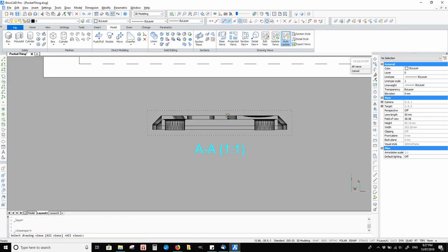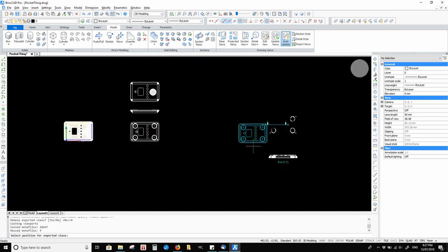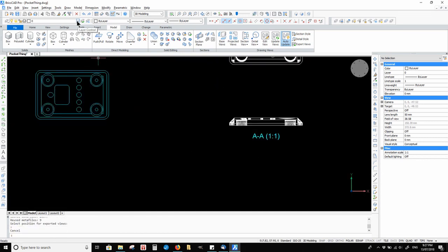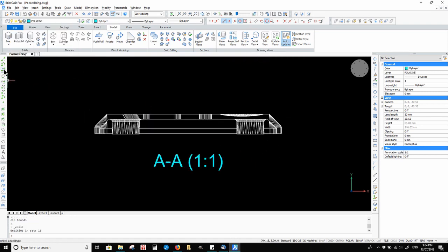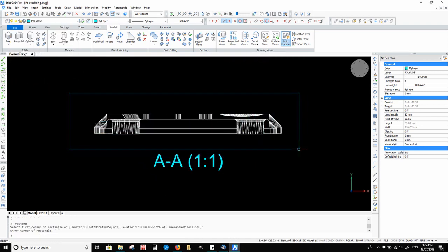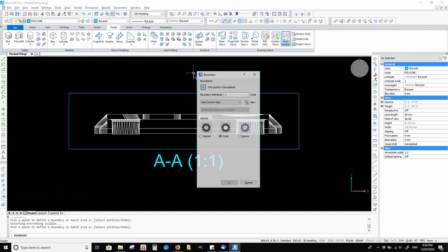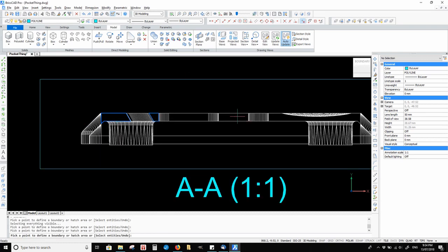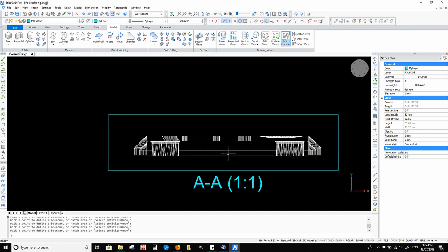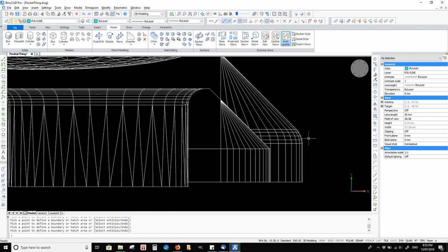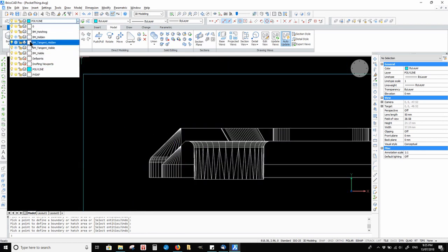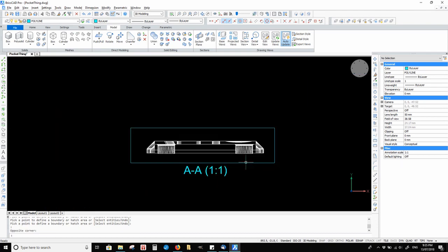Export your section view to model space. Repeat the boundary and overkill and polyline edit / fit process. We can't get a clear boundary for the edge, so we'll use a different, old-fashioned way of getting our lines.